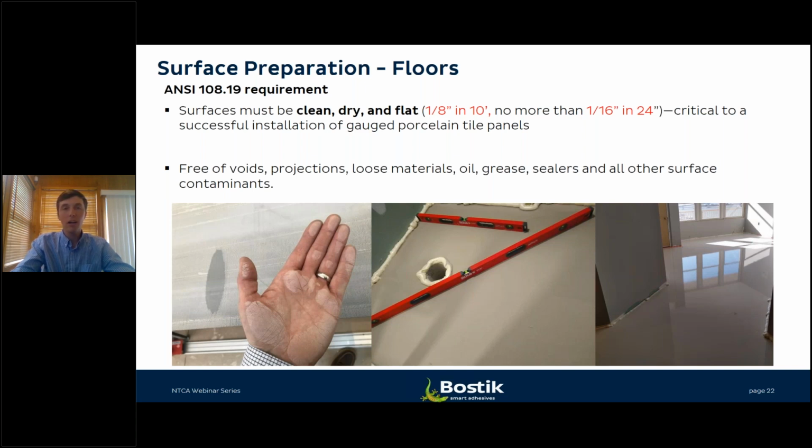That's going to require the same type of floor prep, and often that can be done by the use of a self-leveler. These materials have changed a lot over recent years, and self-levelers have a lot of strength to them these days in the market. They have the ability to get a floor extremely flat, which is an absolute requirement when you're working with large format tiles, as well as herringbone patterns and different Versailles patterns for floors. A vast majority of floors require this type of preparation.